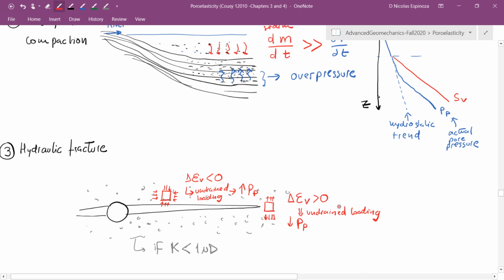And this is also something that is worth mentioning, because I have seen some works in hydraulic fracturing that start with the pore pressure of the medium, of the porous solid, equal to 0. So eventually at the tip of the hydraulic fracture, what they compute is a negative pressure.